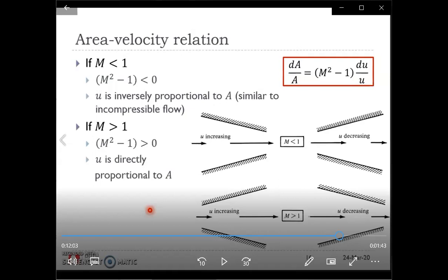since the information propagation cannot be done because the flow field is supersonic, that must happen instantaneously. So a sudden area change can only happen through a shock wave. So that's why we end up with a shock wave when there's a ramp moving into the flow. The opposite is true also. If that kind of ramp is moving away from the flow, generating expansion waves, in that case, what happens is